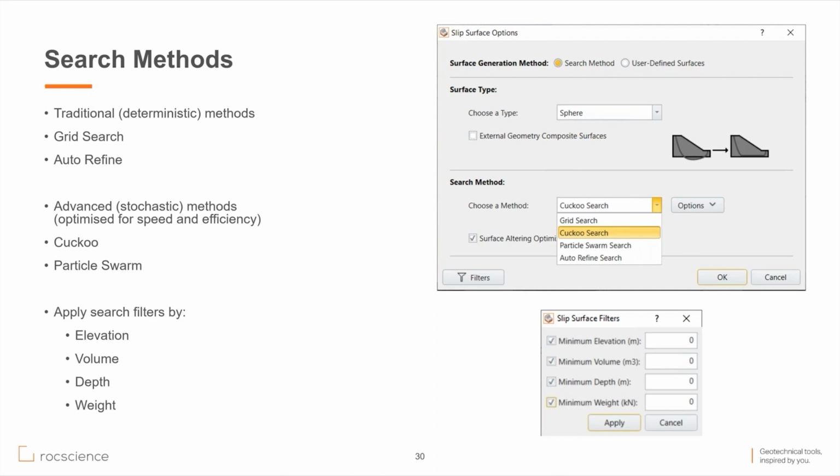How to construct the groundwater surface in 3D to support stability analysis. Good question. We do have another webinar on Rocscience's YouTube channel. It shows how to generate a groundwater table using RS3 and then import that as a surface back into Slide 3. Otherwise, I've seen customers, if they don't have a groundwater surface, use the slope surface as a starting point, drop the slope surface in elevation, and then change the Hu parameters for each material property.